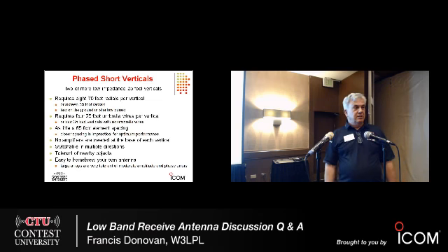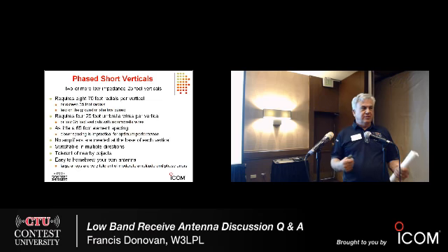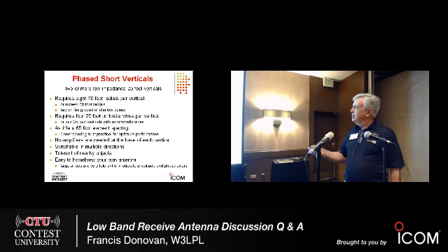Low impedance verticals. They achieve the same tremendous RDF of the high impedance verticals. Unlike the high impedance verticals, they're easier to build. Doesn't take very long to build these. They're 25 feet tall. They require a modest number of radials. I use 8 70-foot radials, and they're in an environment that needs good performance from the radials.